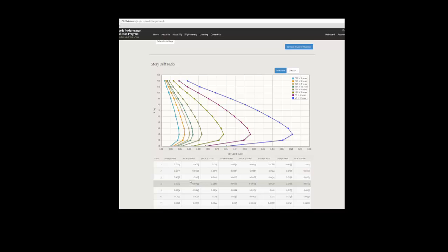But I mean, you would remove the height limitation. You also, frankly, would remove some of the simplification of just how the curve fitting was done in the simplified method. You would also remove having to use a default mode shape, which gives you a lot better estimate of your building-specific performance rather than a default mode shape building performance. So yeah, there are still some limitations because you're doing an elastic analysis primarily.